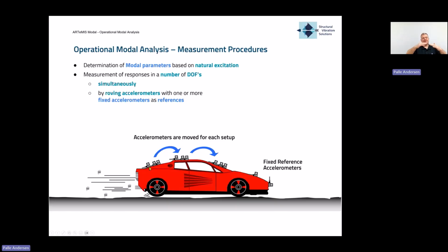Each of the parts or pieces of the mode shape will be nice, but the gluing of them together, the merging of them, will be bad. So you will have some kind of strange looking pieces that, when you animate it, look really bad. So it's important that you have high quality sensors here as well as here. Just use the same kind of sensors everywhere. That's probably my recommendation.